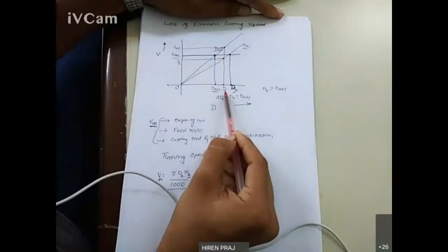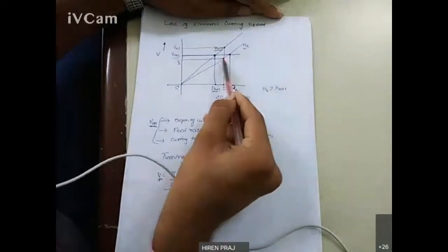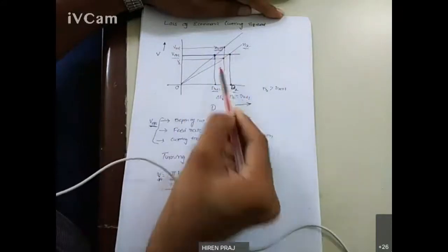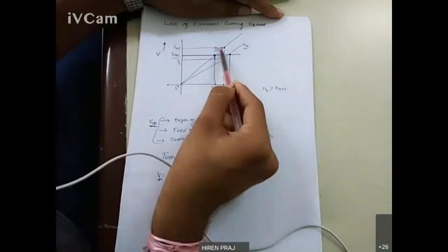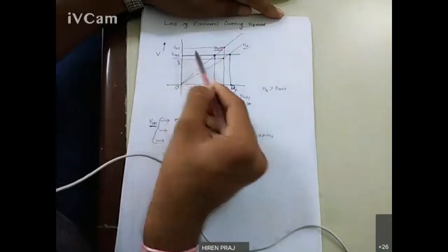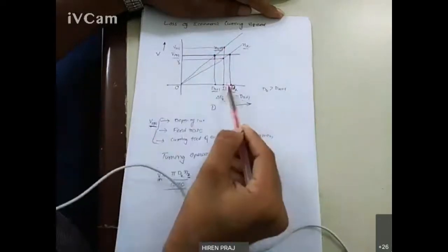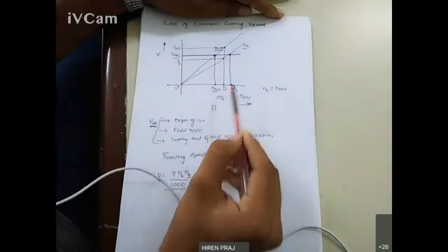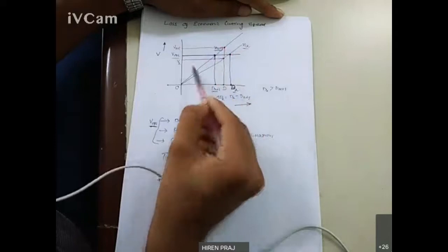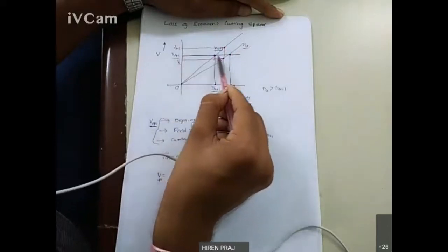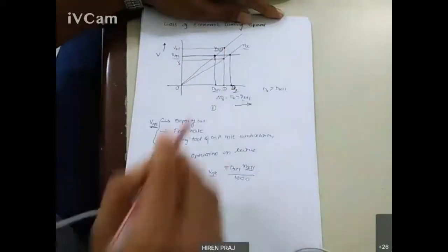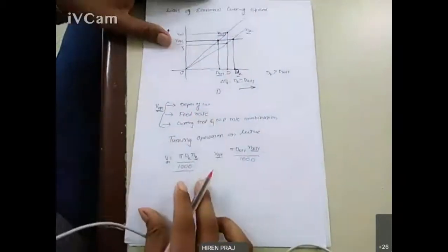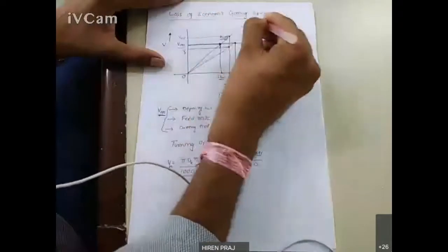diameter. But if I use nx, then again my cutting speed is reduced. If I operate this diameter D by nx plus 1, then the cutting speed is increased. So I am not getting this V optimum. To cover this range, delta dx range, I need to go for some speed which is not giving me V optimum, right? So this is what is called a loss of economic cutting speed. Loss of economic cutting speed.